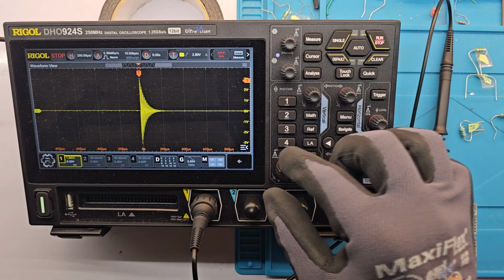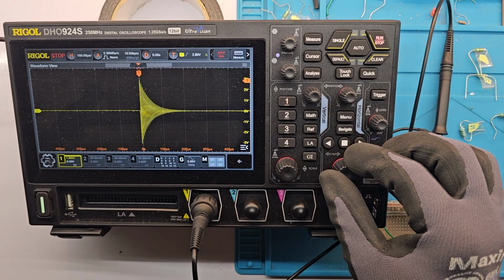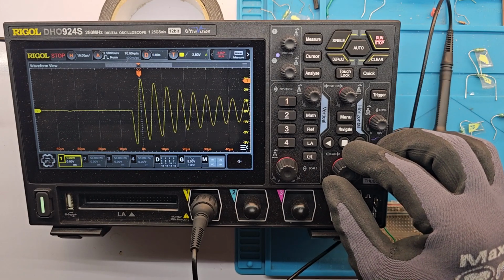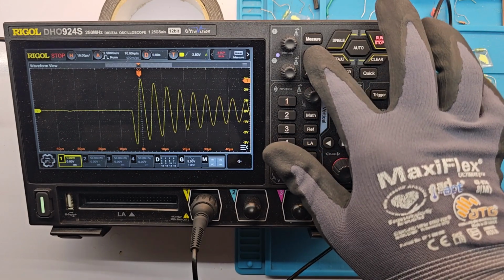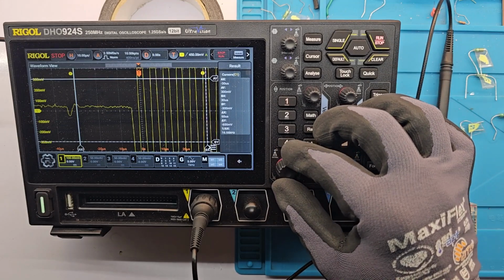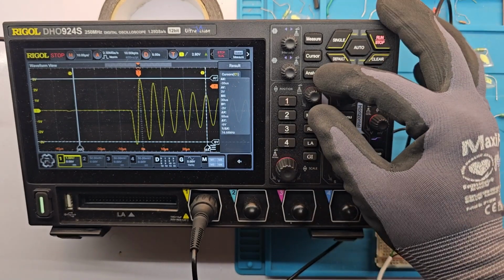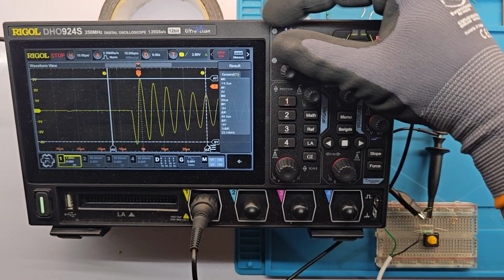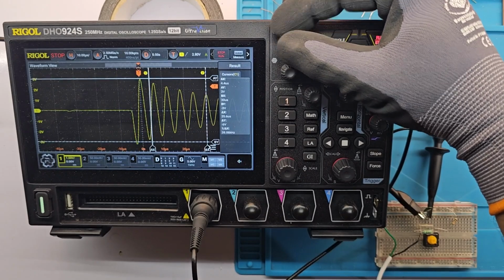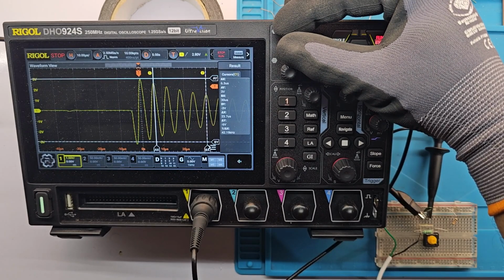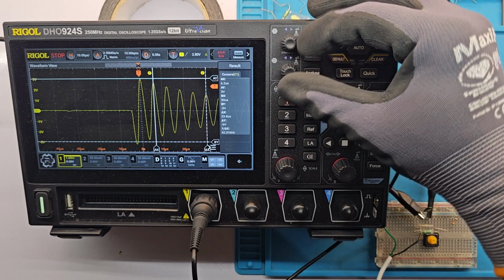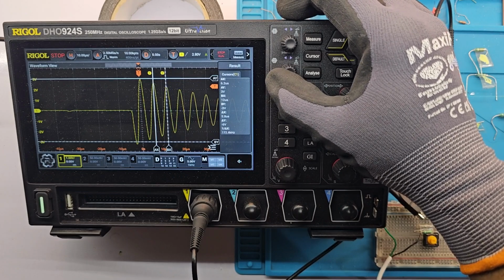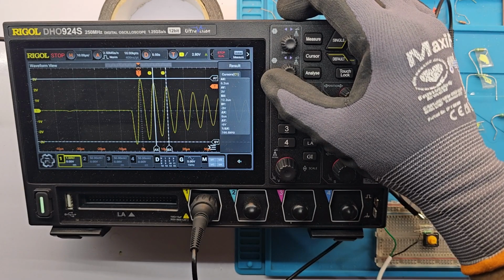If I scale it horizontally, I can see that this is a normal waveform for the LC tank circuit. Now if I go to the cursor, this is the scale, and find out my frequency. The first way to find the frequency is through cursors, X. I'll find a timeline between peak to peak like this.